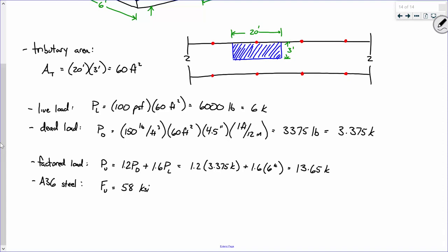You want the building to be able to translate as much as possible. You don't want it to be really, really rigid, because that indicates a lot of force, and we do our best to try and keep that down. So we were telling everybody moment frame, moment frame, moment frame.